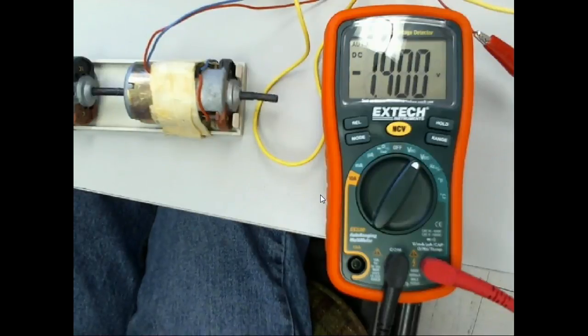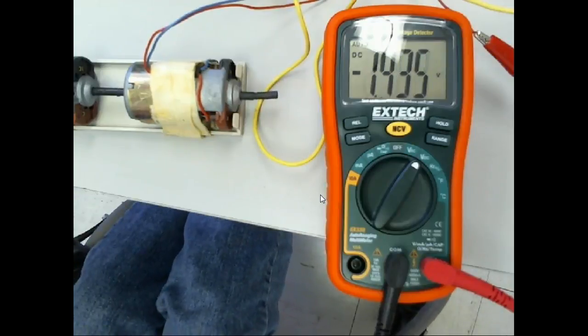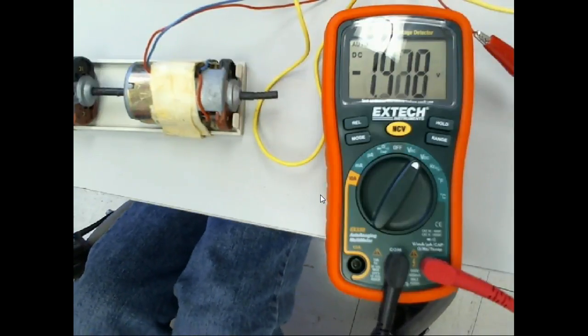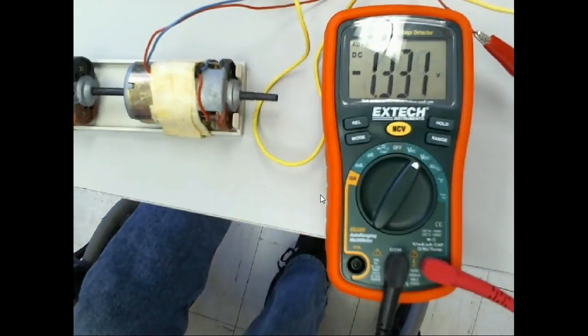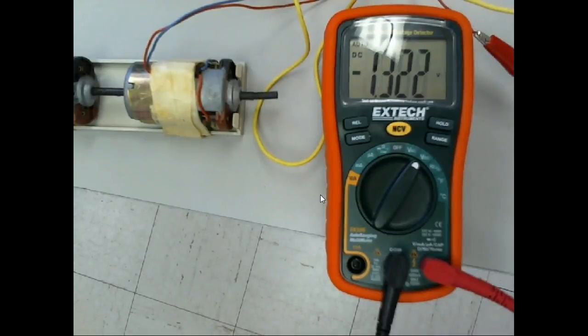So I could take this and run it into a controller. I could run it into an analog to digital converter, and that way I could run it into a computer, right? These are still used a lot, not so much in newer applications, but these were the primary method of closed-loop speed control of motors. This could be AC or DC motors. The tach generator itself could be an AC or DC tach. This is what would be considered a DC tach. Are we okay? Any questions on there?